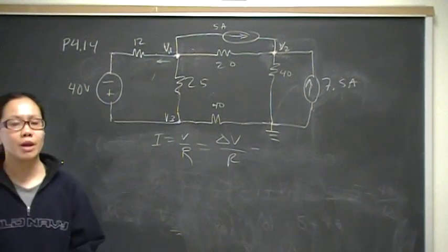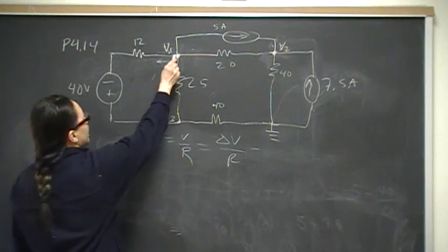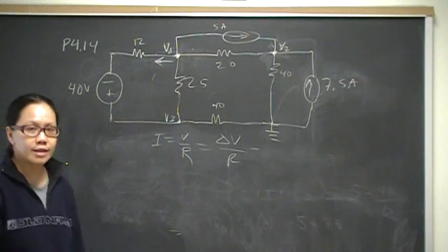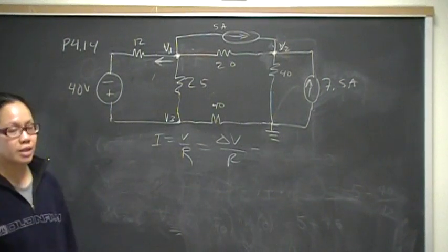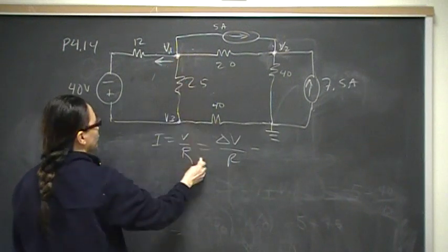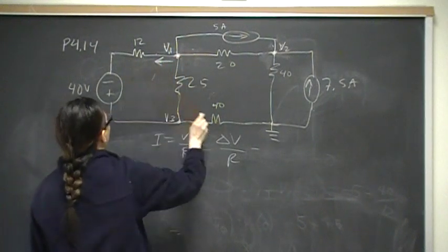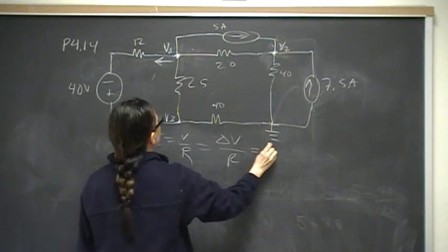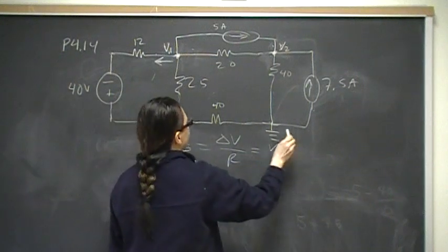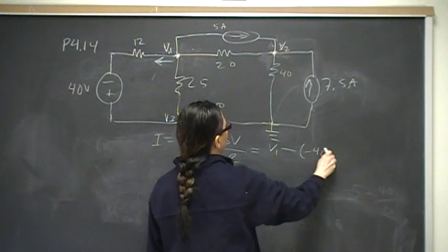The third thing you need to know about calculating a branch current at a node is, the way for this to work is we calculate it as the current is moving away from, that's going to be defined to be the positive direction of the current. Which means that whatever node you're calculating your current at, you start at that node for your calculation. So, for instance, in this one right here, if I want this current, the I sub 12 ohms, I'm going to start with V1, the tail, and then I'm going to subtract the second voltage, which in this case is minus, right? Minus a negative 40 volts.